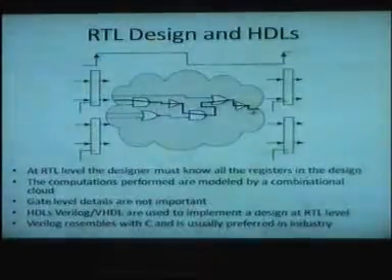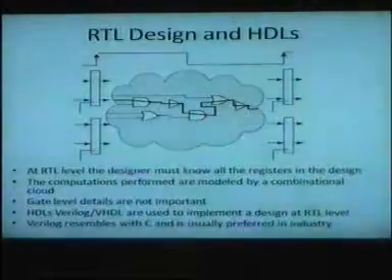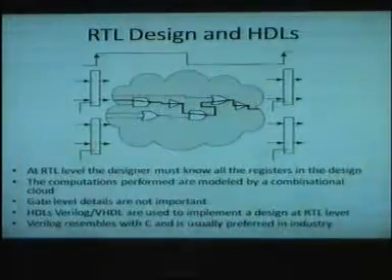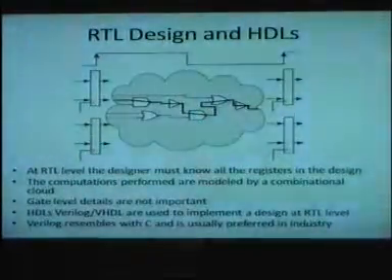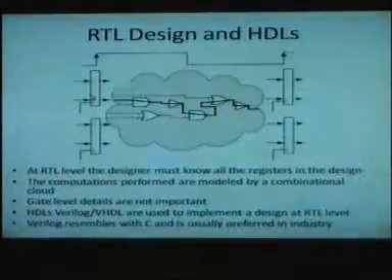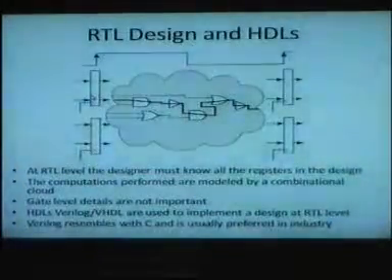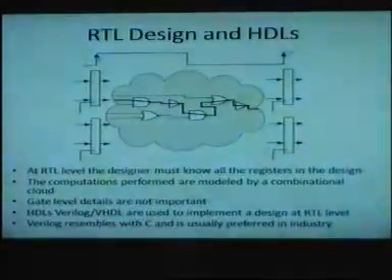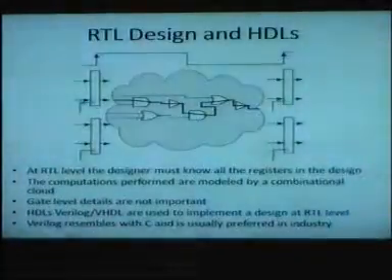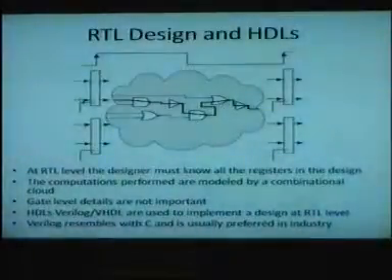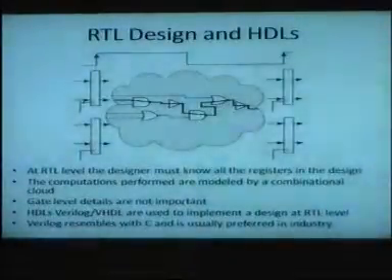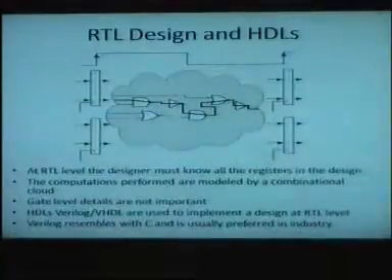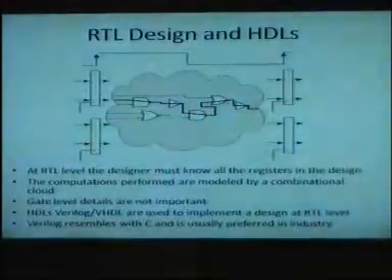So a stable 0 means that all the signals moving from that register have settled. A register has a stable value for 1 clock cycle. So at the positive edge of a clock, as shown here, a value gets from the input to the output; it's a D flip-flop, and as you know, at every positive edge of a clock, it takes the value from the input and passes it to the output.